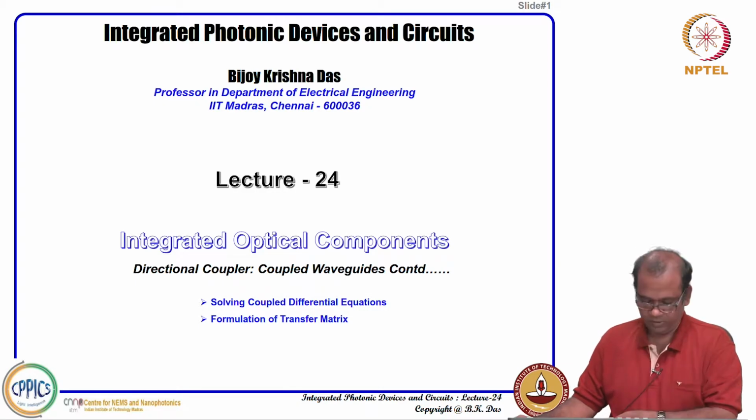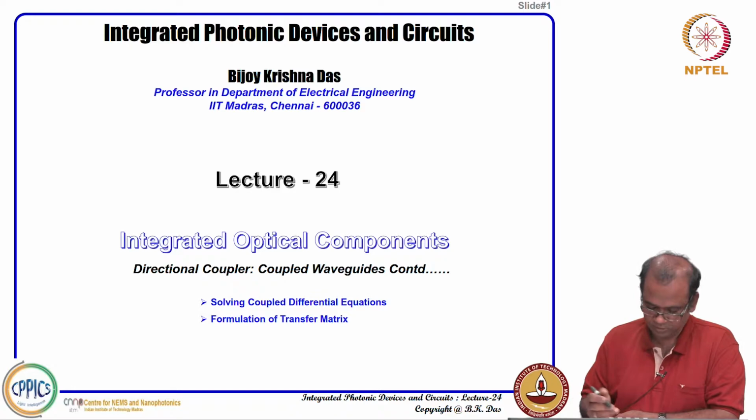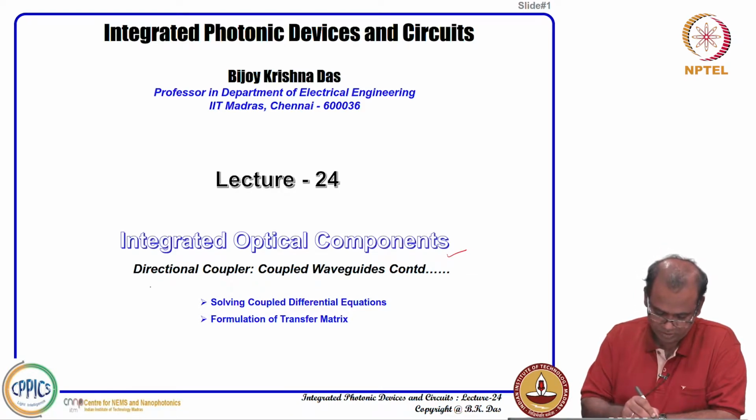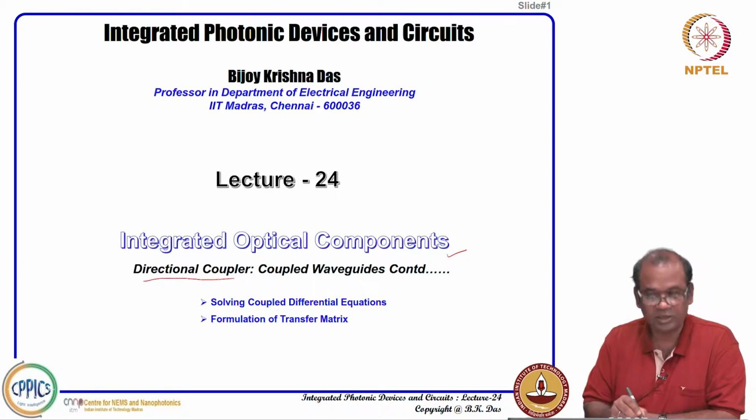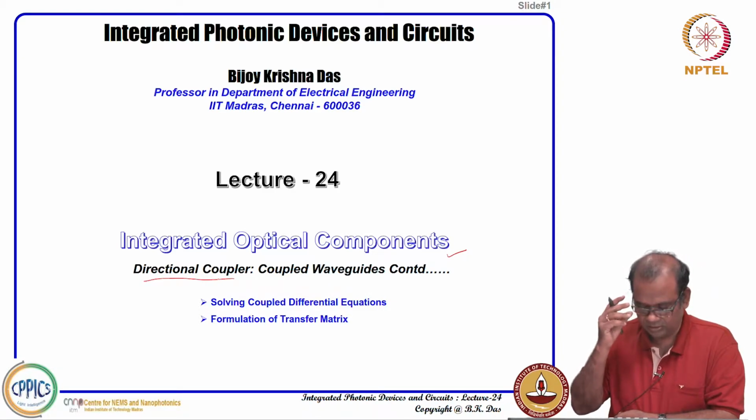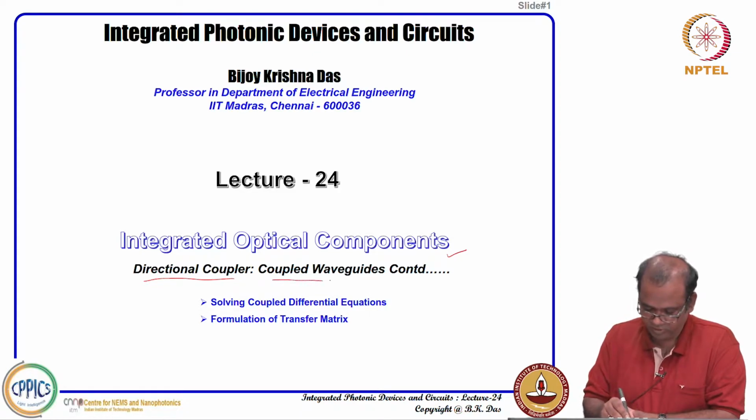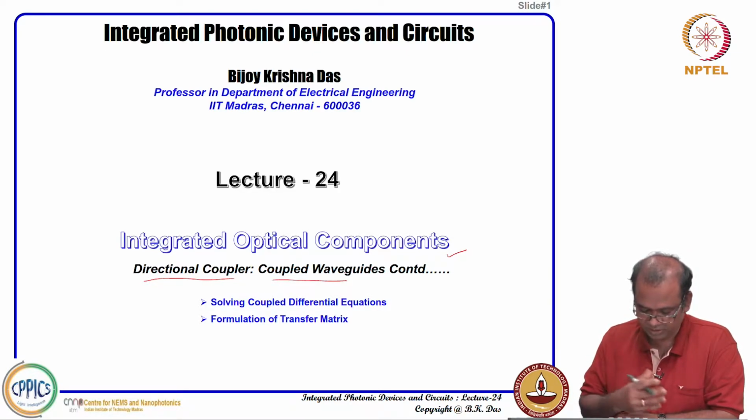Hello everyone. In today's lecture we will continue with integrated optical components. We discussed the directional coupler in the last lecture: coupled waveguides, where we constructed two coupled differential equations between the guided modes in either waveguide.